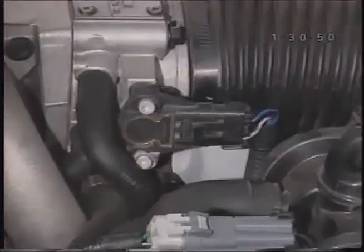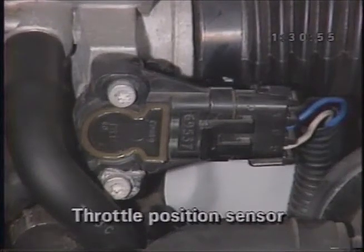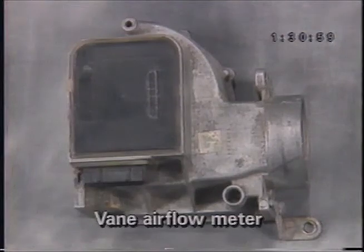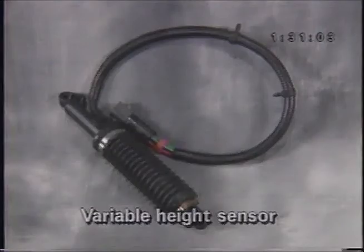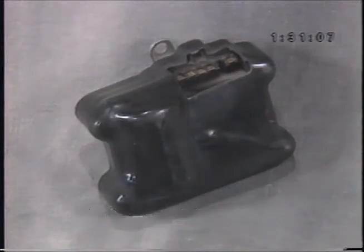In this lesson, you're going to use Scopemeter to measure, examine, and diagnose the output from a potentiometer. There are a number of potentiometers used in automobiles today. The most familiar is a throttle position sensor, but there are others: a vane-type airflow meter, variable height sensor, and a climate control air door position sensor, to name a few.